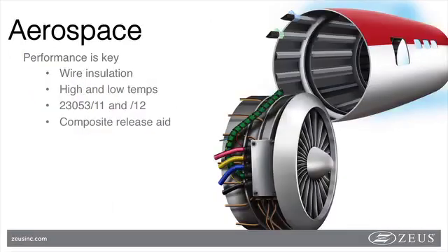Planes have a lot of moving parts and even more wiring. The wire is critical, but insulation and splicing of the insulated wire is paramount. Designers should know that there are great materials that can be made into heat shrinks such as PTFE, FEP, even PEEK, which can be good insulators but also perform well in low and high temperatures, not support fungus growth, have good chemical resistance, and low water absorption.